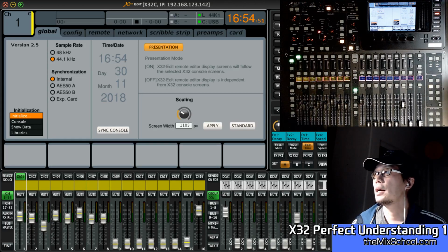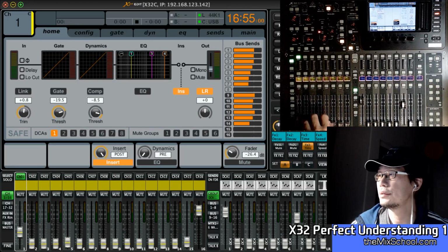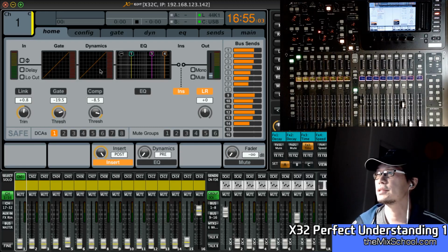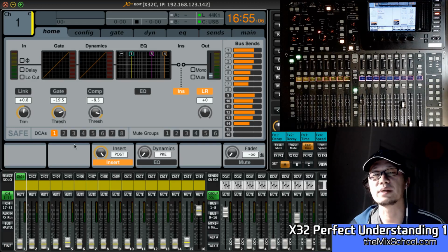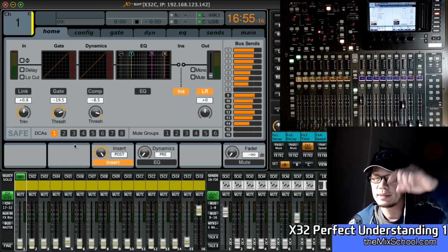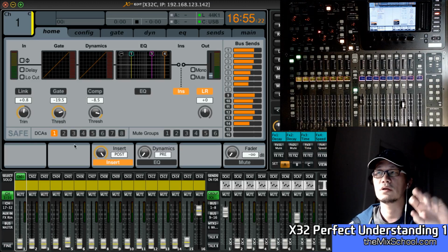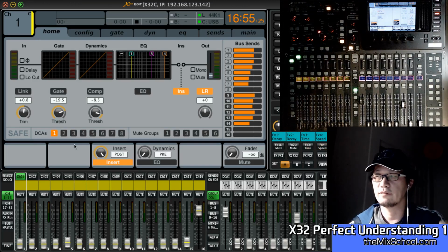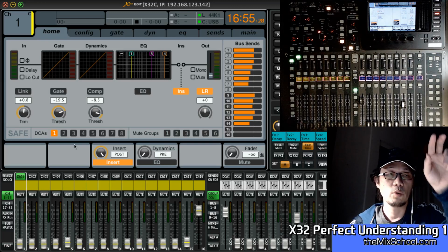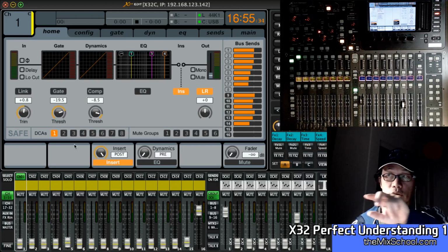All right, let's begin with the home button. So when you press the home button, you will have the individual channel sections, right? So this is a digital mixer. It is not like analog mixers that you already know. An analog mixer has a whole channel strip. So one channel section has the input section like preamp and EQs and mute and pan and faders or groups and all other things in the one section. And if you have a 24 channel mixer, it has 24 of those, right?